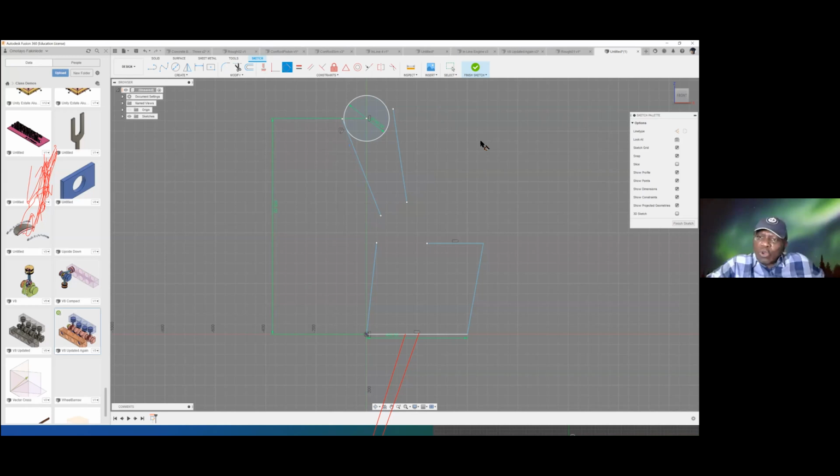Then you use what is called the marking menu. You click your right mouse key and you will see some of the important commands, especially the one you have just used. Say repeat tangent. So tangent here to here. So you can see those two lines are tangent to this circle.